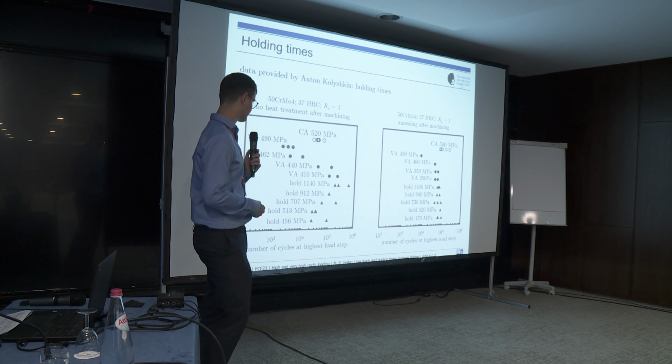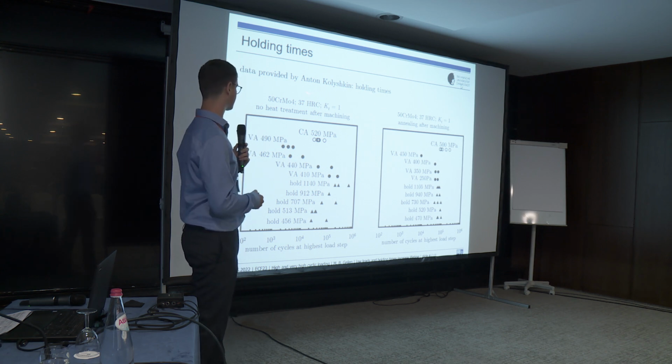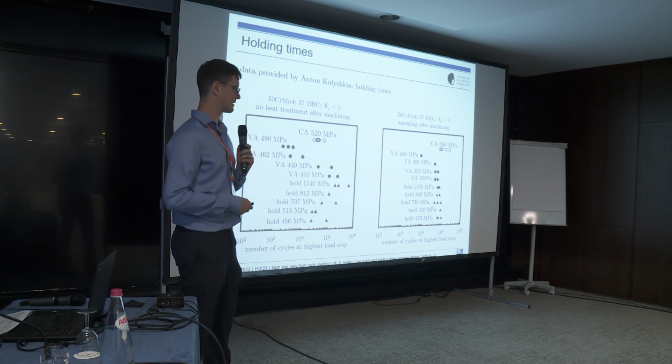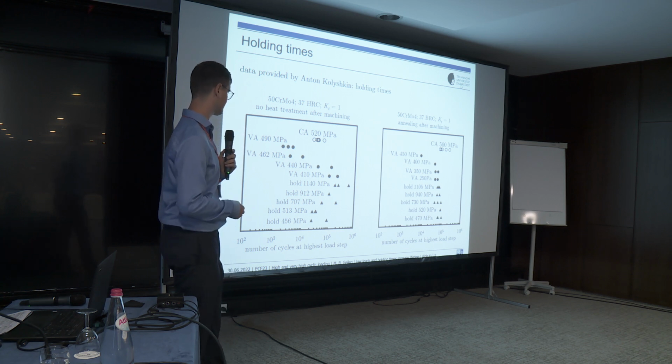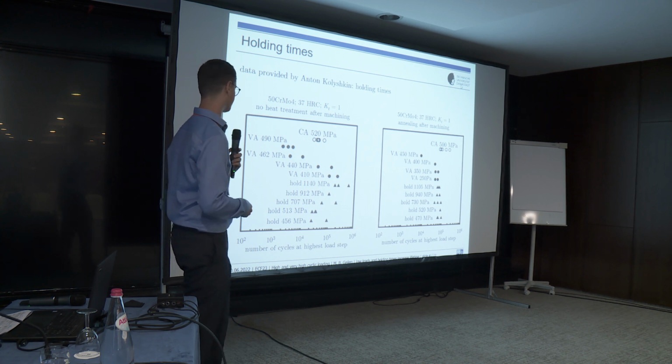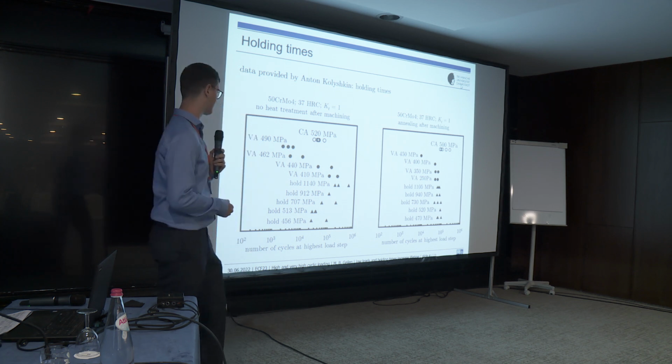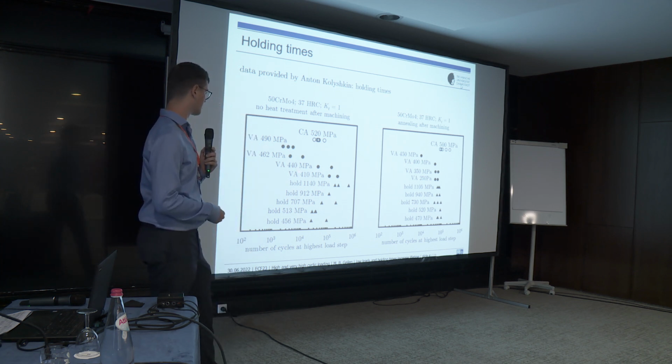Here's another study conducted by Anton Kolishkin from Bosch. He took a 50CrMo4, which didn't have any heat treatment after machining and therefore had some compressive residual stresses at the surface. He did constant amplitude tests just above the so-called fatigue limit at 520 megapascal, and then he combined these 520 megapascal with different variable amplitudes in a two-step test with different lower amplitudes, which were 490, 462, 440, and 410 megapascal.